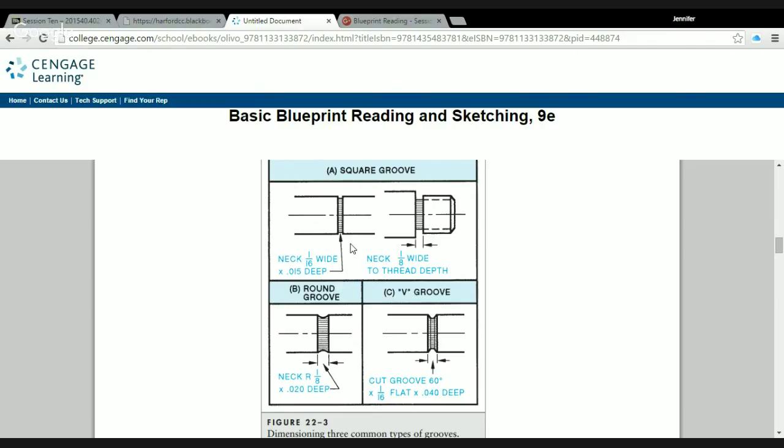And there's a whole big sheet, as I've mentioned several times. There's so much beyond what we talk about in the class as far as how you determine how big to make your groove. If you need an application where you're going to put an O-ring on to keep gas from leaking out of something, how do I know how big to make the groove? Well, that's already worked out. Depending on the diameter of the O-ring, there are equations that get you to how wide and how deep to make the groove so that the O-ring does its job and keeps the gas or the air or the liquid in place and not escaping out into an area that it shouldn't be.